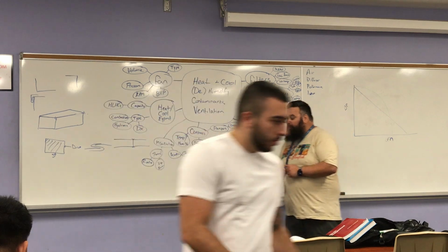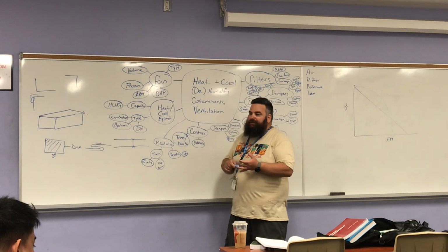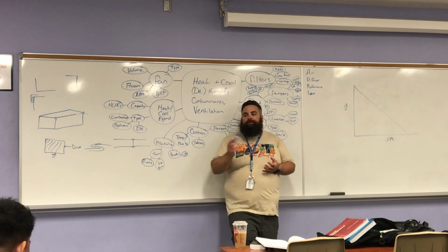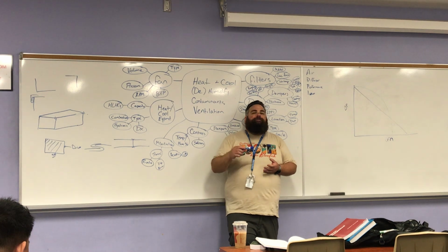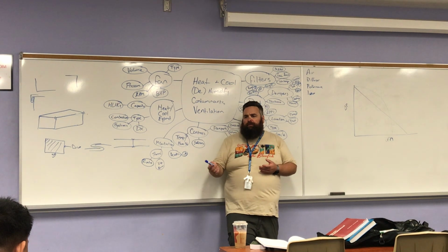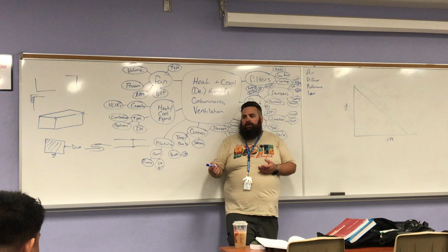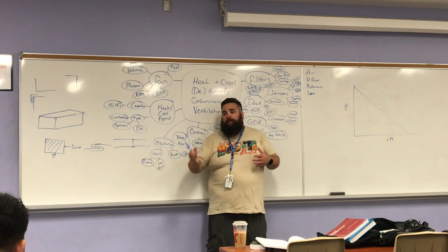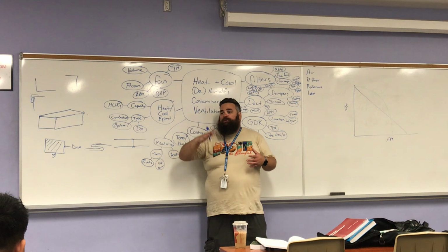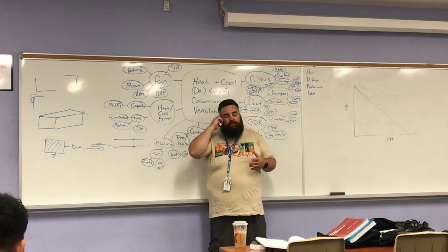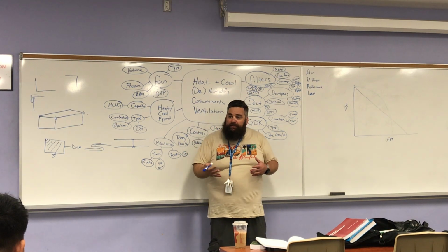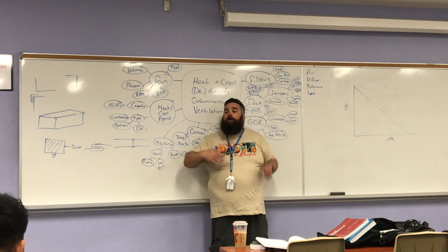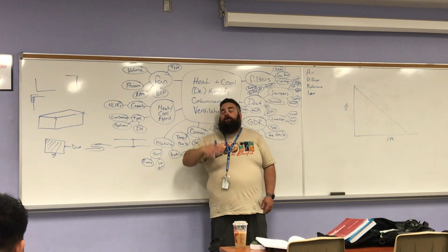Yeah, so typically what we do is we acoustically line the first 10 feet from the fan, supply and return, or the first 10 feet from, let's say, you know what a VAV box is? A VAV box is a type of damper. It's a variable air volume box. It opens and closes to adjust the amount of airflow to the space. That'll cause a lot of turbulence off the discharge, so we want acoustic lining and flex duct to absorb some of that.